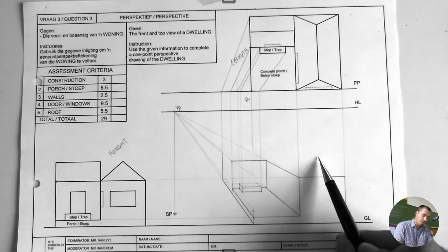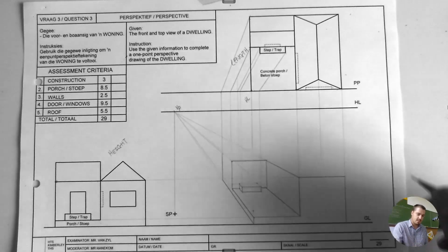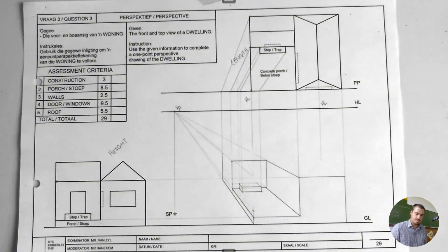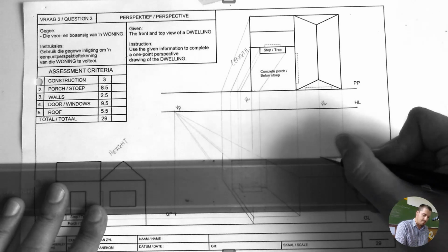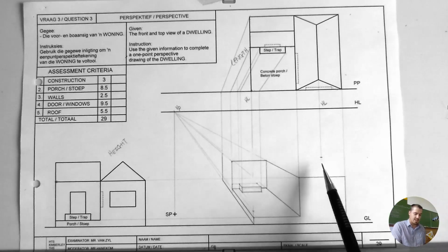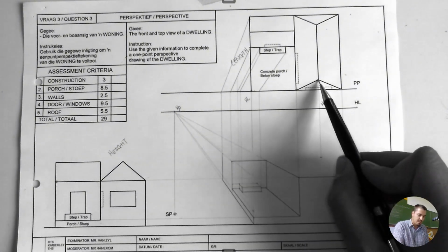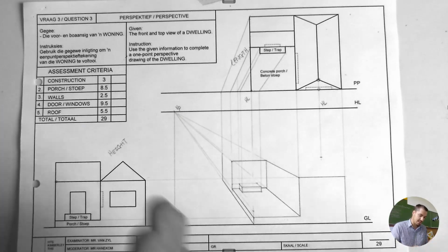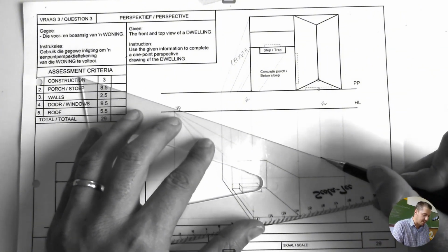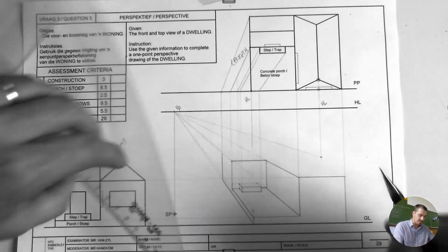So in order to get the roof point here, we are going to create a height line for the roof specifically. So I'm taking this point straight down, right? This is a height line. Then I'm taking the height for the roof. So there is the apex point, and I'm making a mark on that height line I just made. So typically you would just connect these points up to there if this point was on the picture plane. But now it isn't, right? It's slightly moved away. So this point now has to go to the VP. So on this line is where I'm actually getting the height for the roof.